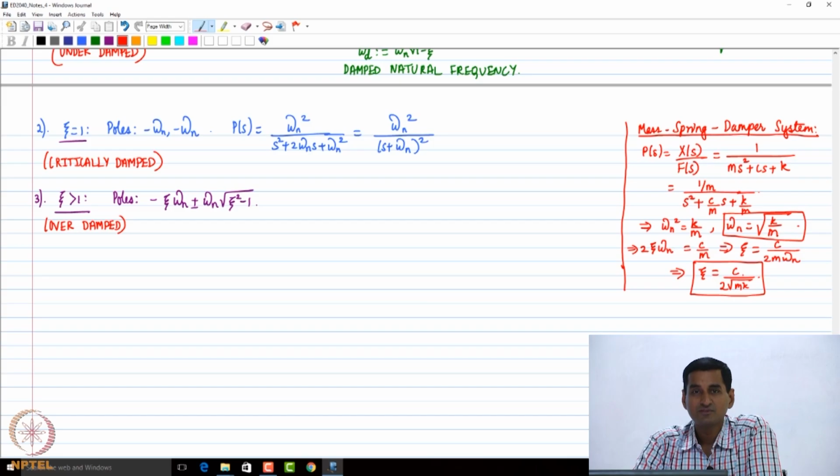So that's good. So what is natural frequency? If you do not have any damping to begin with and no external excitation, the frequency with which the system's response would oscillate if there were an initial perturbation, what we call the free response of the system.